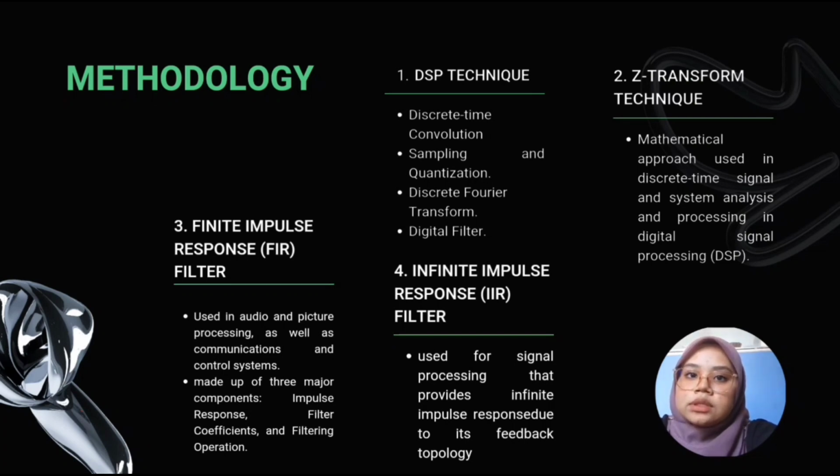IIR filters provide advantages such as efficient implementation, fewer coefficients, and are excellent for applications demanding sharp roll-off and accurate frequency control. However, they may display non-linear phase responses, which can change the timing of various frequency components. Overall, IIR filters are an effective tool for digital signal processing due to their efficiency and versatility in frequency response design.